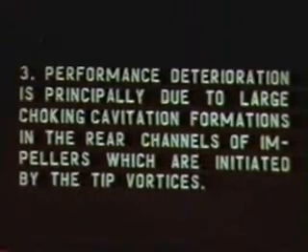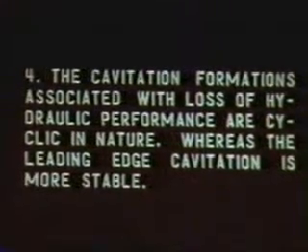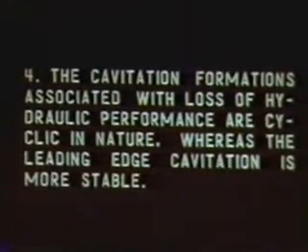Performance deterioration is principally due to large choking cavitation formations in the rear channels of impellers, which are initiated by the tip vortices. The cavitation formations associated with loss of hydraulic performance are cyclic in nature, whereas the leading edge cavitation is more stable.